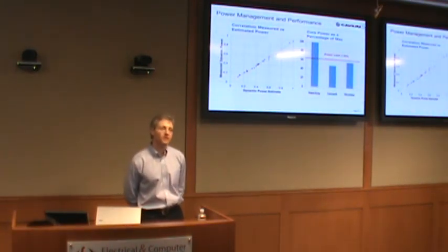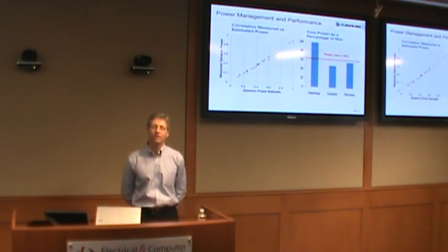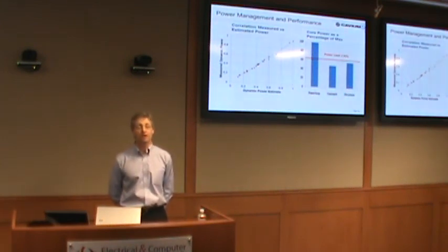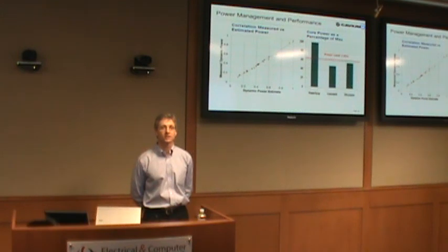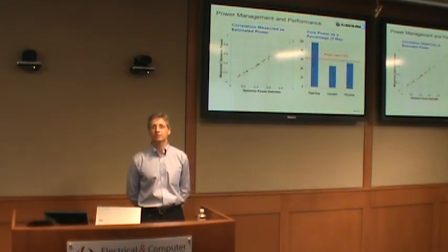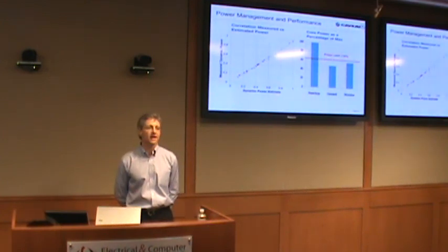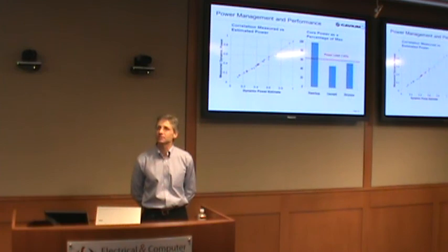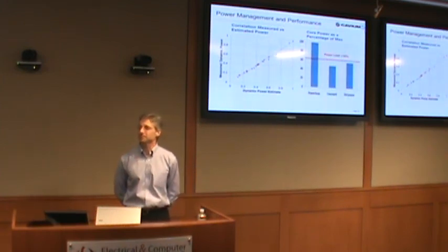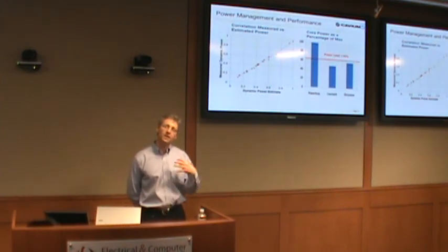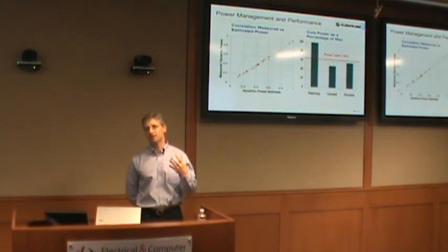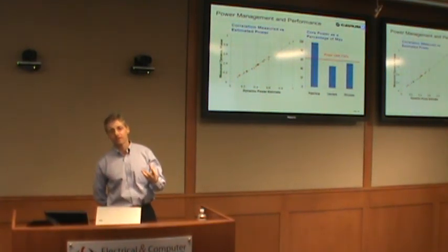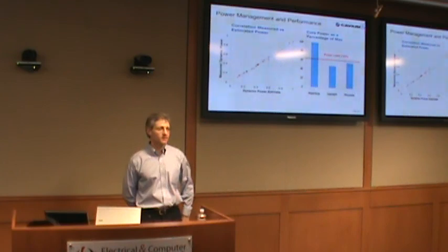Since we have this hard limit on the power, we can have a hard limit on the power consumed by the chip itself. So that's a big benefit for us. We don't want to design our power system for an application like the power virus, which isn't really practical. We want our users to design their systems for a practical power consumption level.